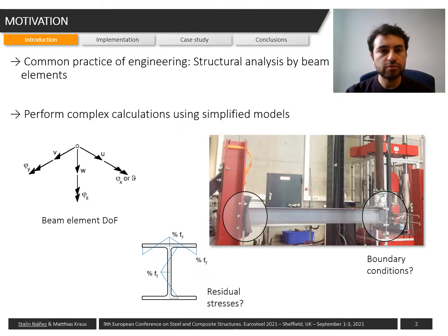The motivation of this work comes from the field of civil engineering, in which normally we use beam elements for defining big structures and for performing normal calculations daily. Why do we do that? Because it's simpler in terms of defining the structure, and also it's faster when we want to perform the calculations. If, for example, we would like to do the same using shell elements or volume elements, we would find difficulties in defining the boundary conditions such as the supports and the application of the loading.